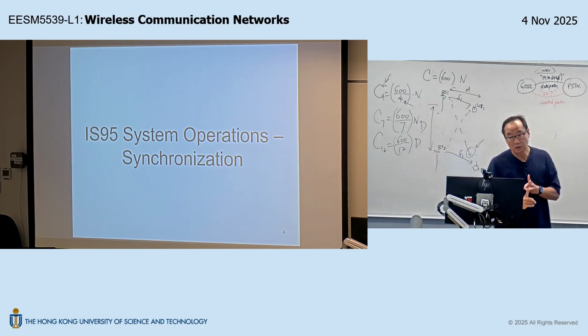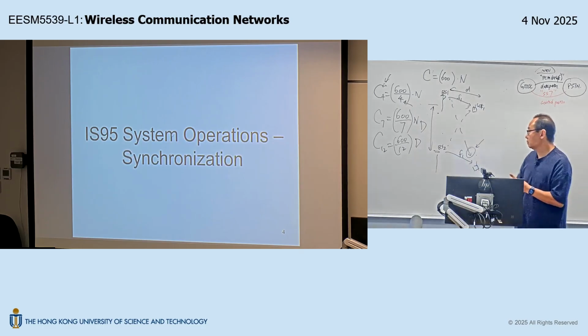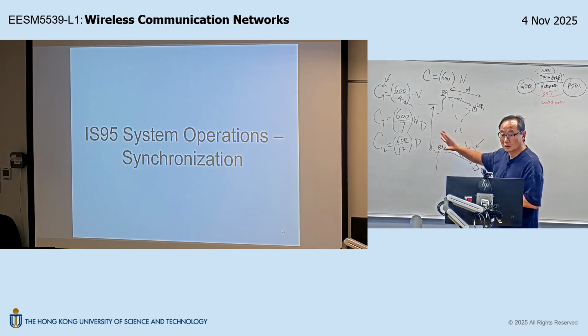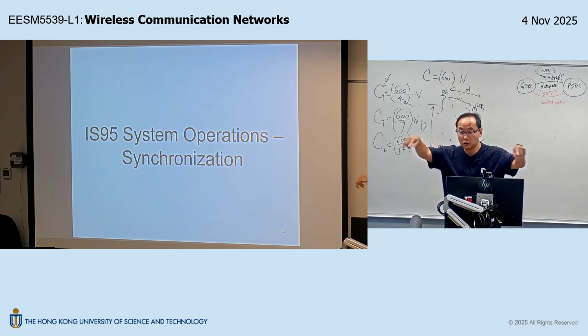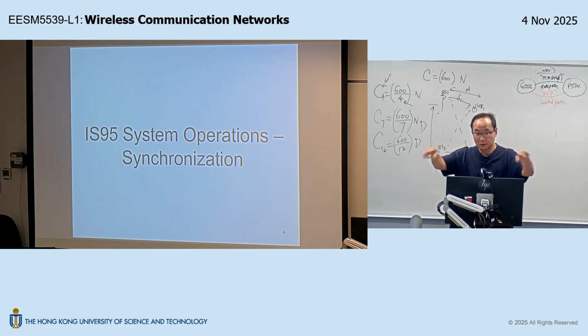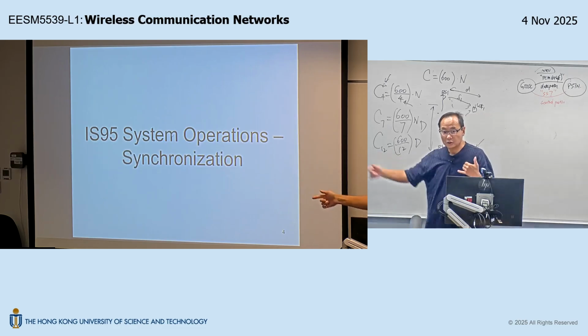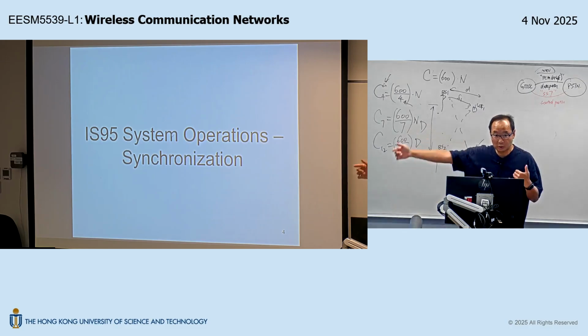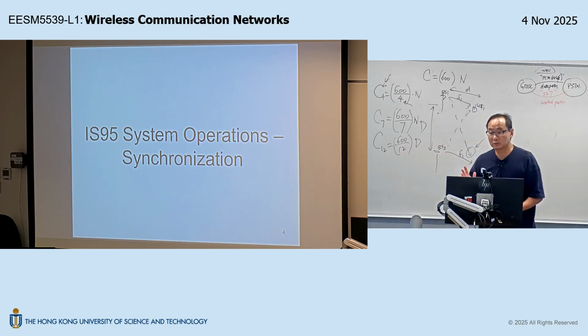The reason that we need to worry about handover is exactly because of cellular architecture. With cellular architecture, the coverage of a base station is very limited. So if I start a call in a certain base station, but then I keep on moving, as long as I cross the cell boundary, my call will be interrupted, right? So the handover arrangement is to make sure that despite the mobile crossing the cell boundary, this kind of mobility will be transparent to the voice user.